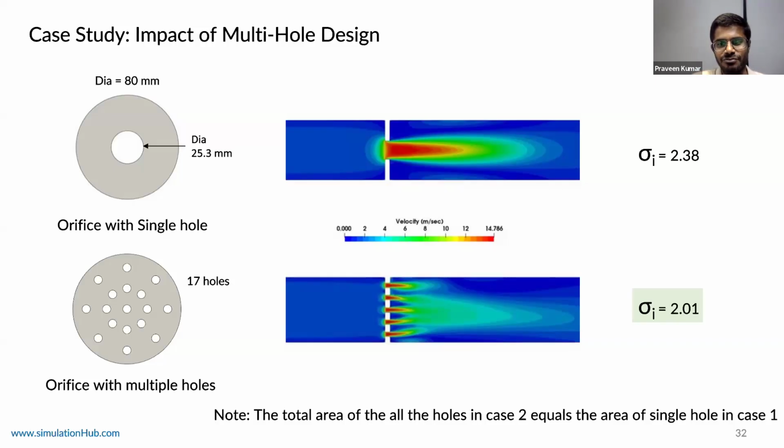The incipient one is right in front of you: it's lesser and better in case two and higher in case one. What is the state of the cavitation index? Both upstream and downstream pressure are the same in both cases for both designs. What is the sigma? It is exactly the same.